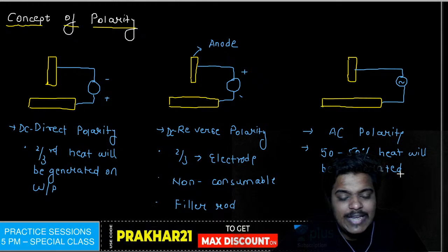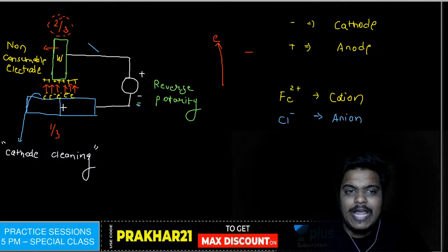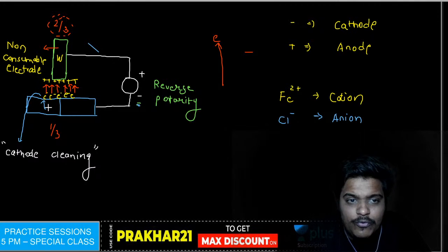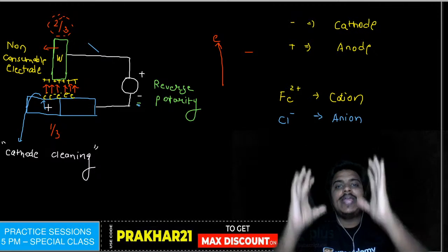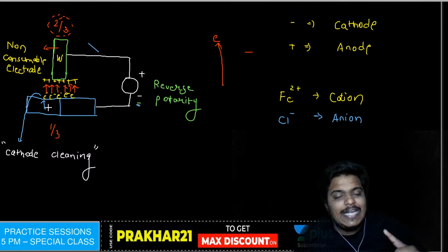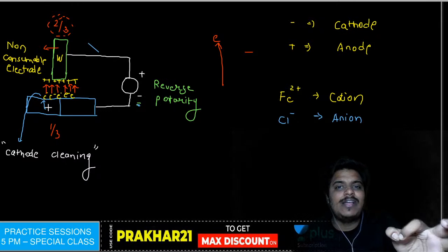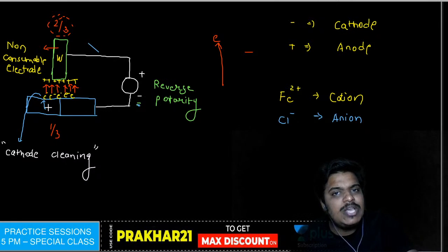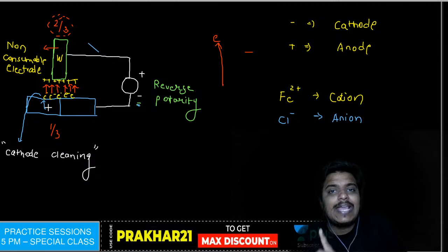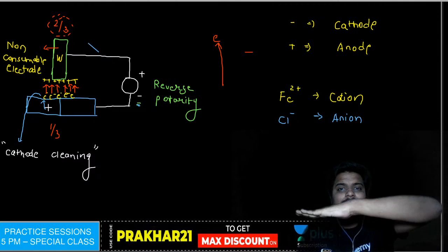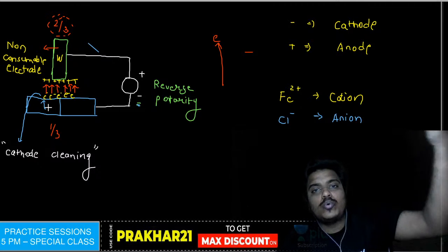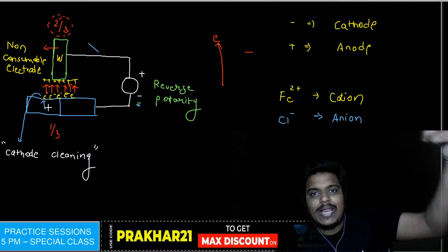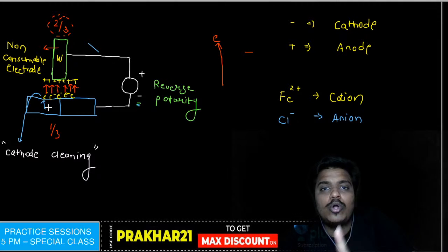Why, Mayur Khatri, I have told you why reverse polarity: because when you are having reverse polarity, electrons move from the workpiece towards the cathode, and while they are moving in the upward direction, the kinetic energy is high when they are leaving the workpiece. We use that high kinetic energy to break the layer, because without breaking the layer they cannot go up to the electrode.